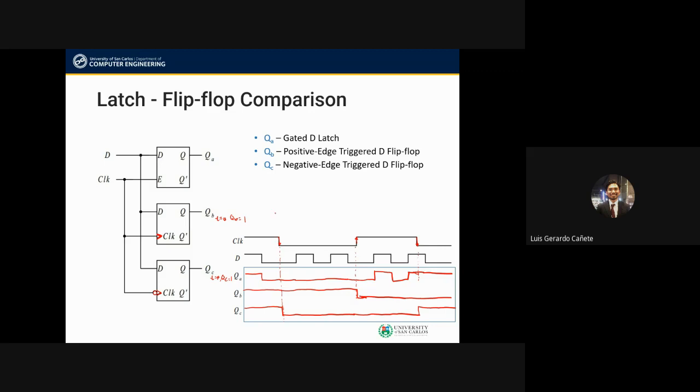So your D-latch has something called a setup time. So the setup time is a minimum amount of time for the value of D. So notice that when the falling edge happens here, I always said the value of D here, right? Just right before the edge.